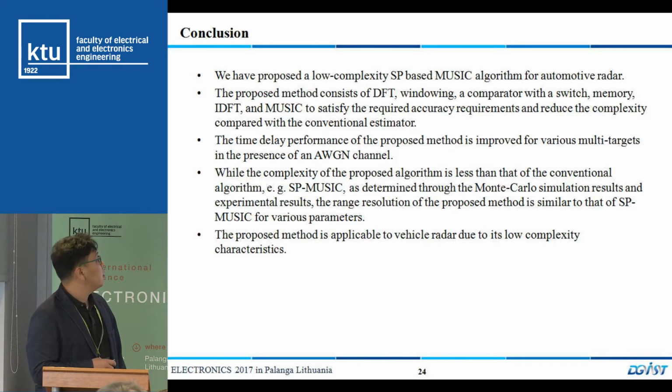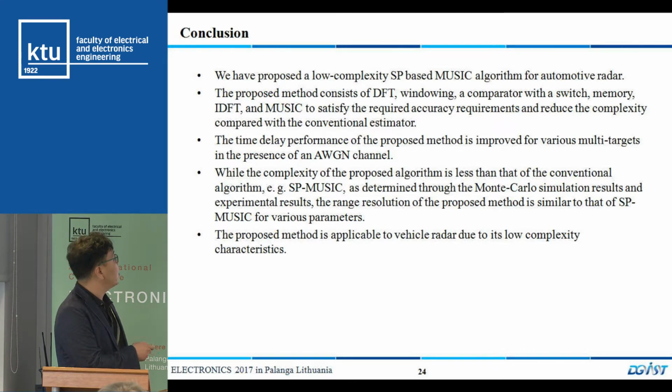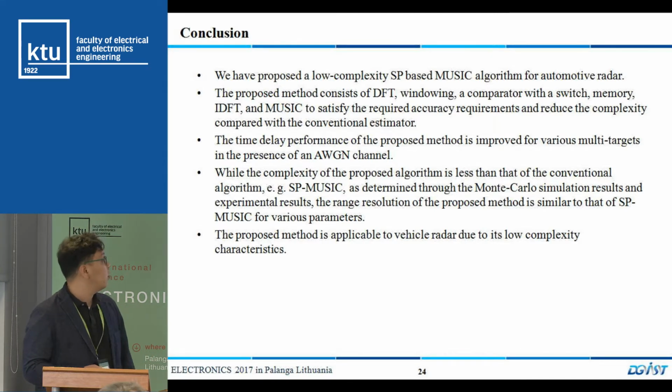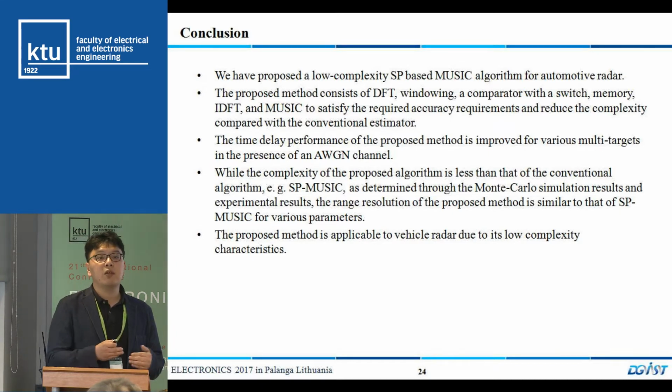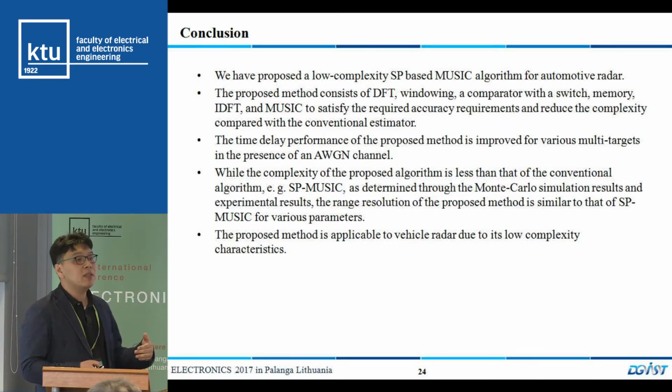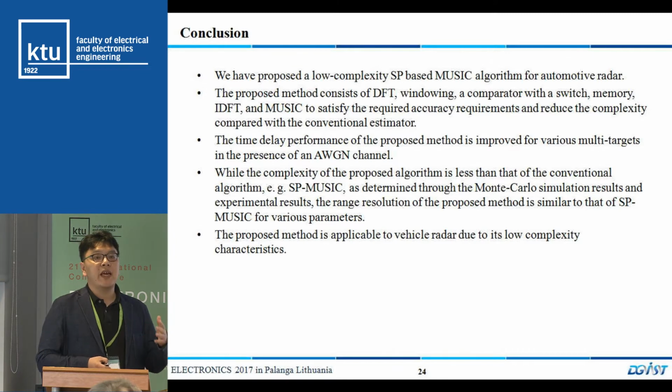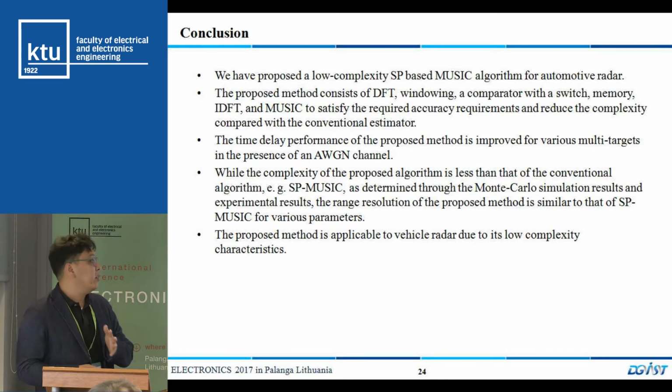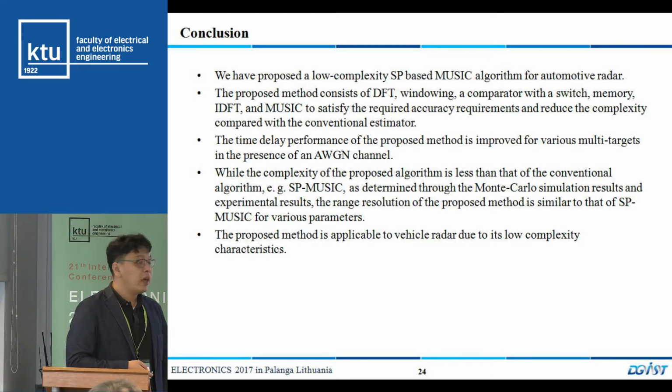And to verify the performance, we did the multi-target AWGN channel Monte Carlo simulation. Finally, we can know that the spectrum partitioning algorithm and the proposed algorithm have similar performance, and the complexity of the proposed algorithm is less than the others. The proposed method is applicable to vehicle radar due to its low complexity characteristic.